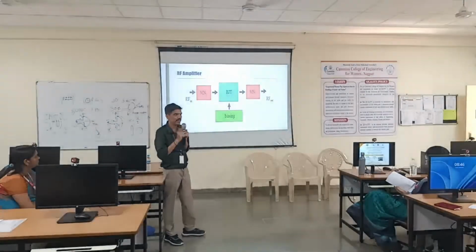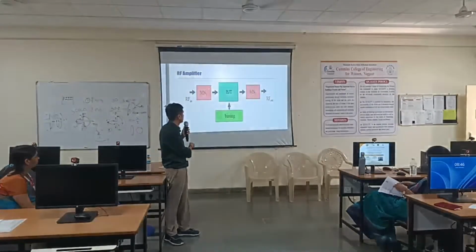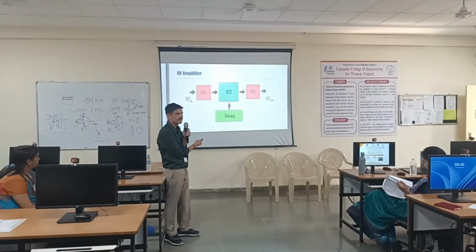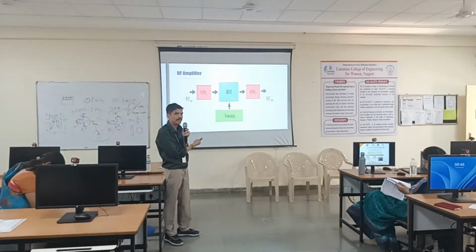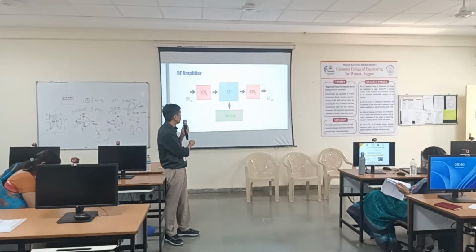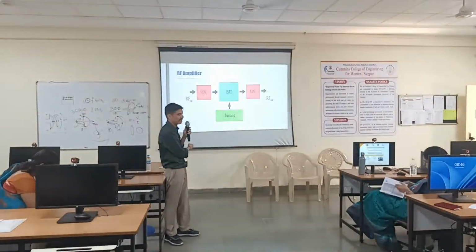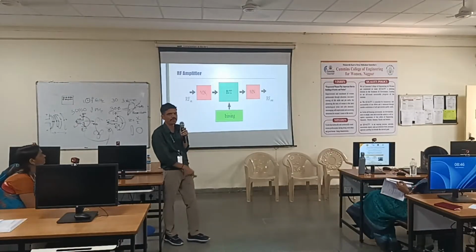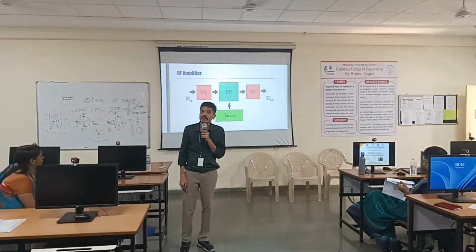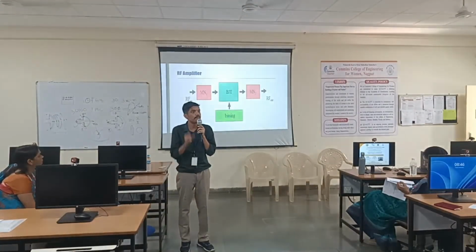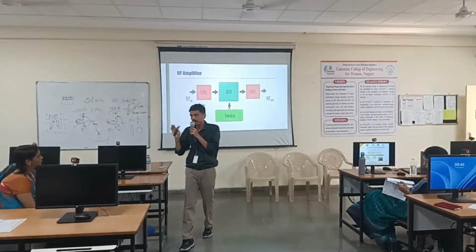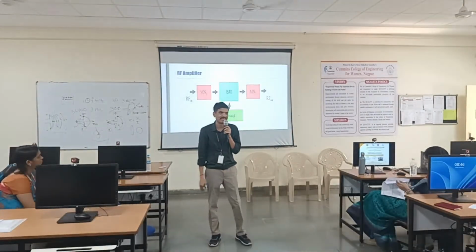Now, we know that the job of a PA designer, or any amplifier designer, is designing matching networks. So what do you do when designing a matching network? You match the complex impedance of the output of the transistor with the real impedance of the output, which is 50 ohms. Then how do you do that? Can you match a complex number with a real number by some means?